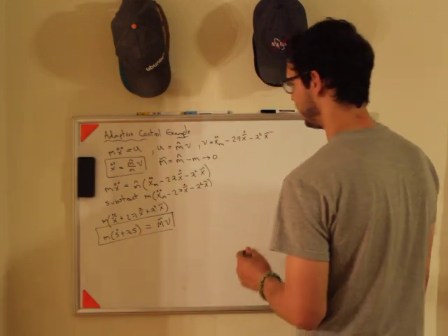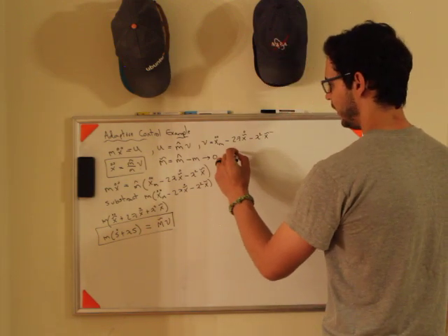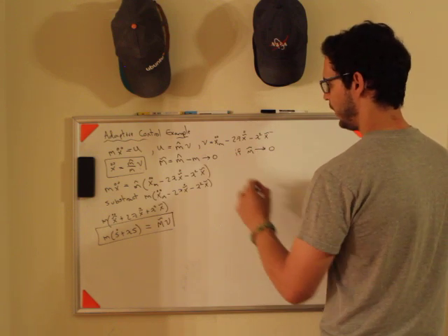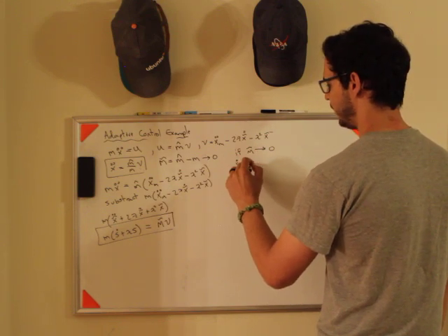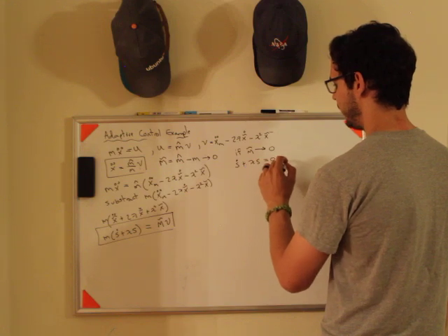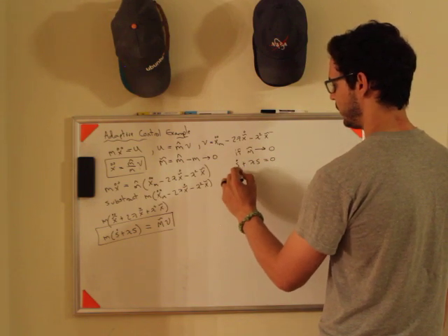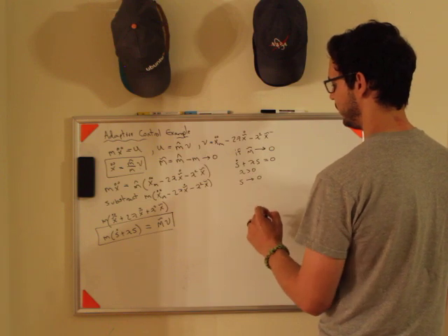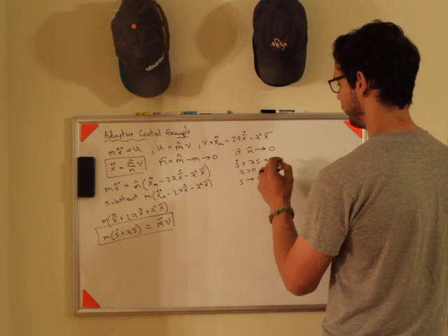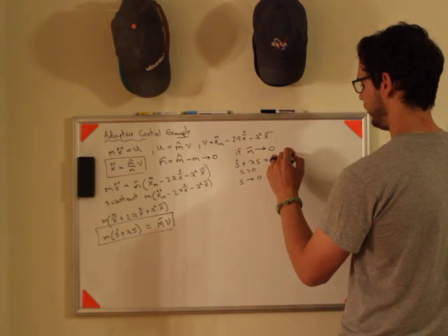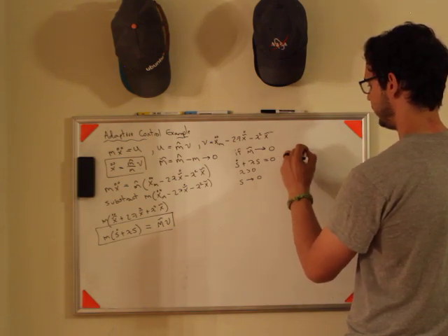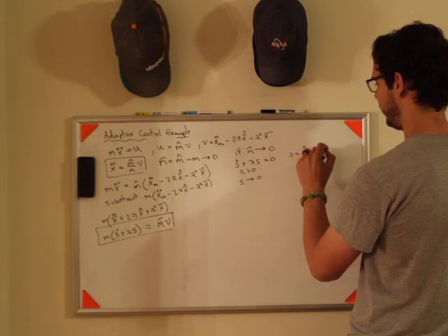Okay, so let's take a look at these closed loop dynamics for a second. If m tilde goes to 0, then that means that s dot plus lambda s is 0, has a 0 forcing function, which means as long as lambda is greater than 0, s is going to tend to 0. If s tends to 0, remember that s equals x tilde dot plus lambda x tilde.